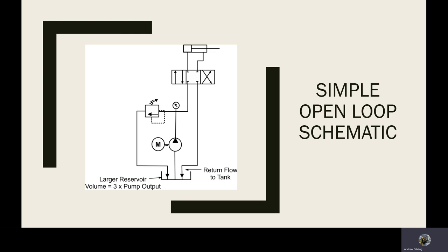Another thing you can find when you have PRVs, pressure relief valves, going off all the time is a chattering sound when you move your actuators. Pop, pop, pop, pop, pop, pop, pop. That's telling me that there's a problem in the system. You may have a restriction that's causing that pressure.